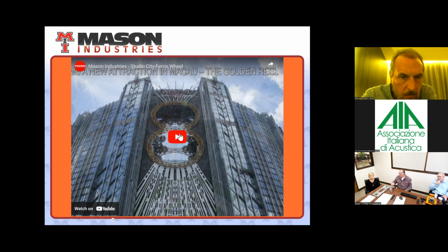That being said, I could turn this on, you could look at it, but one of the last things we do is a lot of military work, and this is an isolation pad that's designed for United States Los Angeles class subs, so that there's a singular frequency that the submarine will operate at, and the machinery doesn't call out any specific tones that would make that sub uniquely identifiable. So we have multiple bearings under all the equipment in these US submarines. And we do a lot of military work.